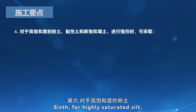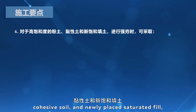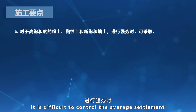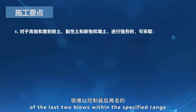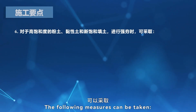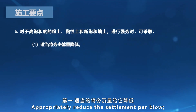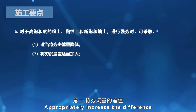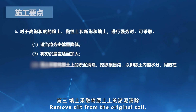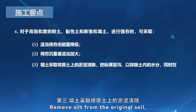6. For highly saturated silt, cohesive soil, and newly placed saturated fill, it is difficult to control the average settlement of the last two blows within the specified range. During dynamic consolidation, the following measures can be taken. Appropriately reduce the settlement per blow. Appropriately increase the difference in settlement between blows. Remove silt from the original soil.